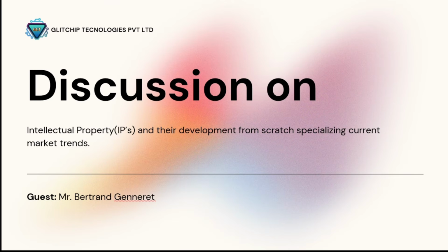But the advantage is that soft IP offers more flexibility for the customer. Soft IP is also simpler to develop, so it's less expensive too, because you don't have to make a test chip in each technology node to be silicon proven. It can be customized per customer requirements, which is another advantage compared to hard IP.